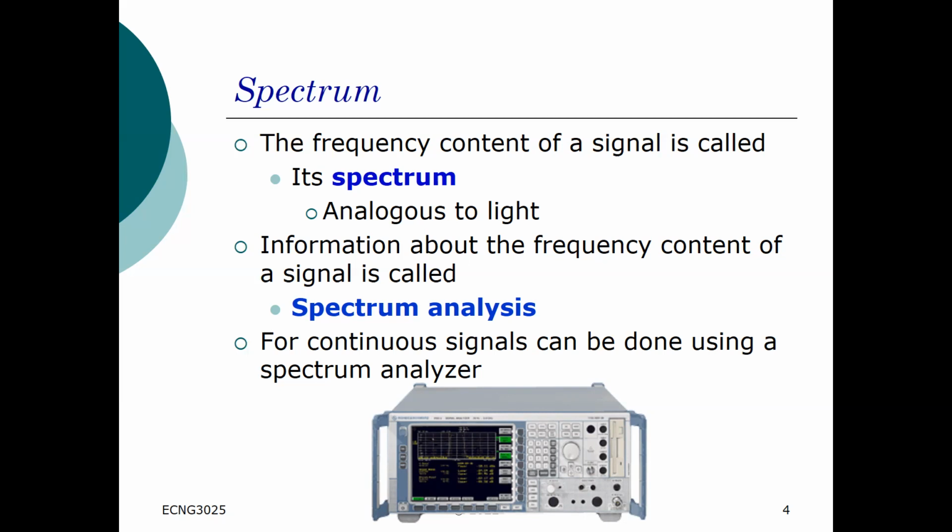And what it does, it takes a signal coming in, it passes it through a series of filters that you can adjust the bandwidth and the center frequency and so on. And then it displays the amplitude coming out in continuous time on a screen. Of course, now the line is blurring between doing that in real time and doing that with digital signal processing, because of how fast both analog and digital systems can now operate.